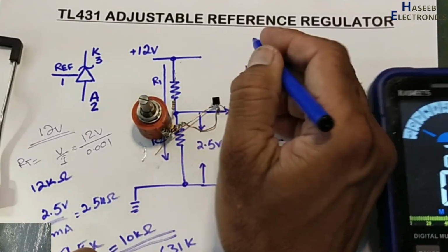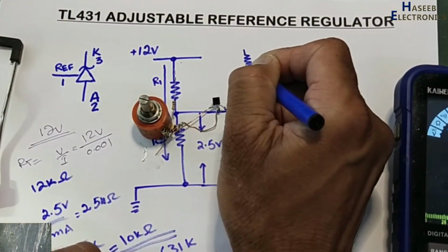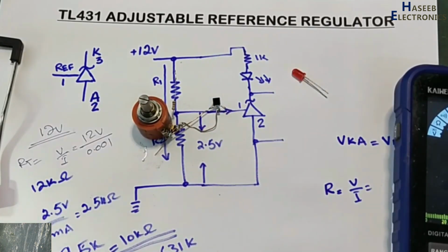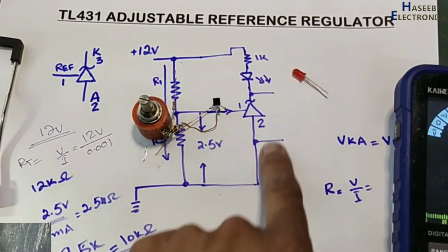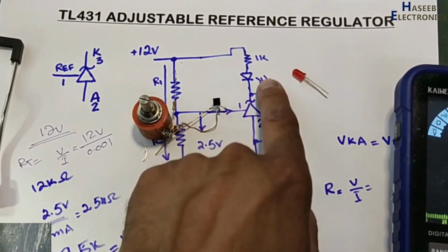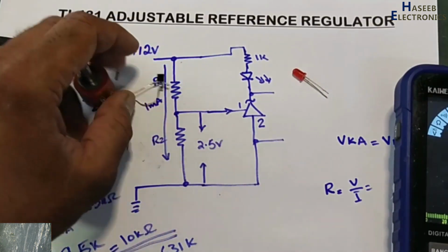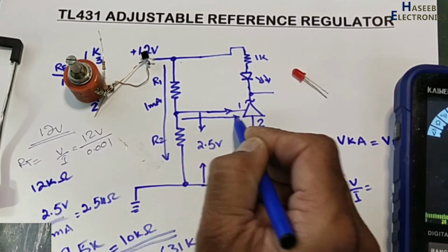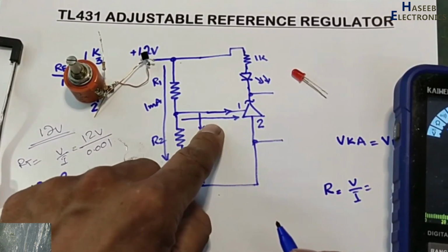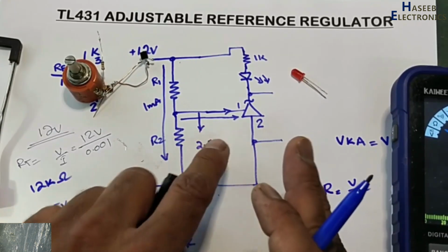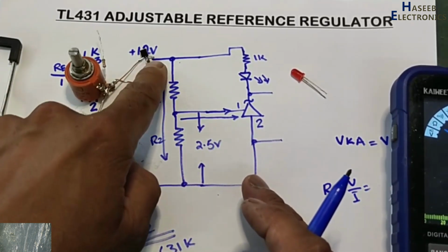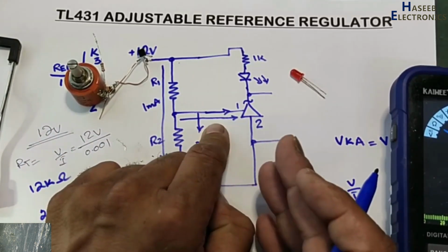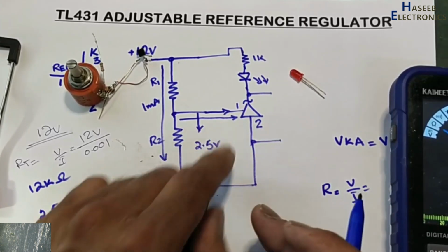As I discussed here, we need a 1K resistor here with this LED. When we connect 1K, approximately 7.7 milliampere current will flow in this path. Now we have two currents, one here, the second, 1.8 microampere maximum here, the reference current. It will not make a big loading effect on this voltage divider, because here is approximately 950 microamperes. So 1.8 microampere will not make a big deal.